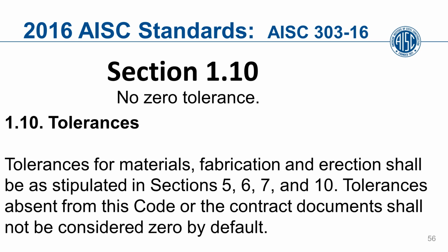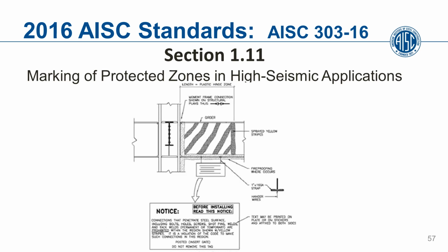Marking of protected zones in high seismic applications. There is a protected zone in every high seismic application, and there's a requirement to mark those. They usually are marked during construction, but sometimes those marks got covered up by fireproofing. And as time went on during the life of the building, nobody knew where those protected zones were, and items were attached in those areas.